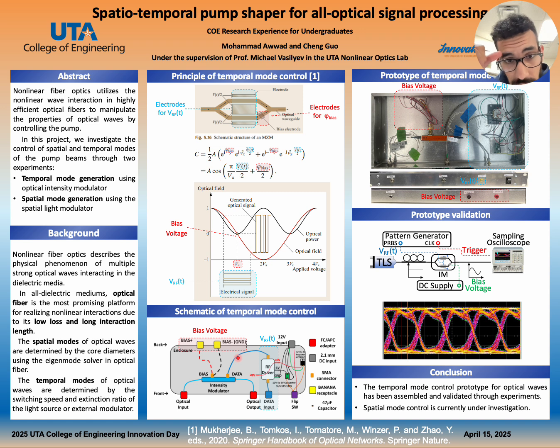In terms of the schematic, we started building the electrical side first. We have a 12-volt input coming into here that goes into a 12-volt to 8-volt regulator. This ensures a stable 8 volts going to our RF driver, as well as a negative 5 volts just to give us the bias that we need to create our amplification. We also have a switch here to allow us to pick whether we want this amplification to be involved or not.